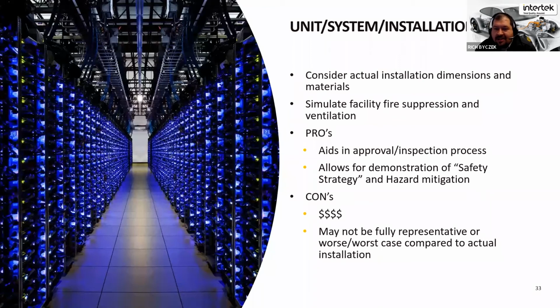From a regulatory standpoint, this may be considered the best case. So understanding that if you can find ways to test module and smaller system level to evaluate the cell propagation, that's preferred from the lab and manufacturer standpoint. The trick there is that you have to demonstrate to a regulator that you did try to get the worst case actual situation.